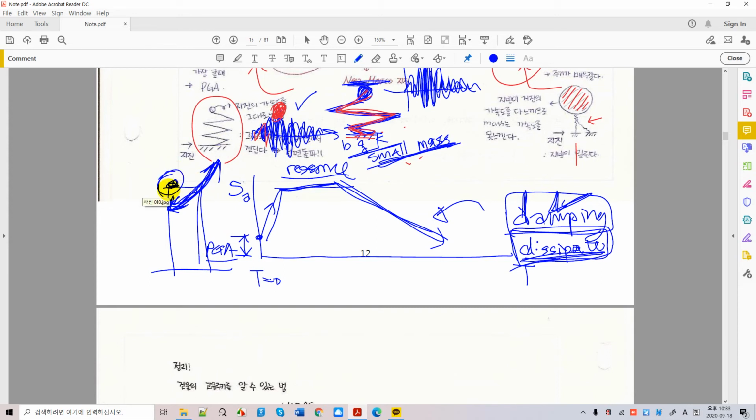damping, right? We saw door damping, door hinge, right? The door hinge provides damping so that the door opens, goes down, and stops where it's supposed to stop. Beautiful, isn't it? So that's a hinge and damping. So damping is very important for things to stop. Okay, same thing for a building. A building has inside damping. So this damping stops building vibration, building movement, in a very short time, right? So when you have damping, the more damping, the faster stopping, right?